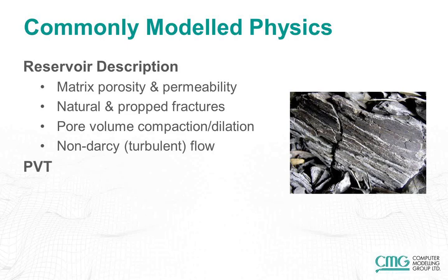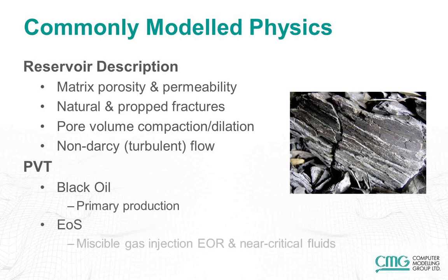And looking at the phase behavior, we need to account for things like going over the dew point or the bubble point. So the type of fluid that's in the reservoir will determine how we want to model this when we look at the simulation. So if we have a dry gas or a black oil, we may use our IMEX simulator, which can typically be used if we're looking at primary production mechanisms. If we have more advanced mechanisms, such as enhanced oil recovery, or we have near critical fluids, then we may want to look at an equation of state simulator, such as GEM.